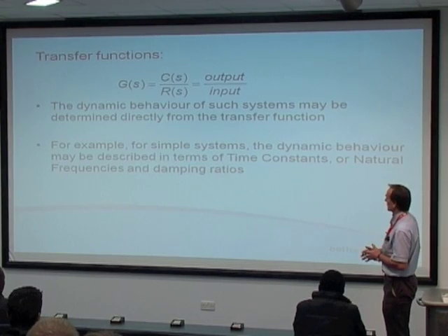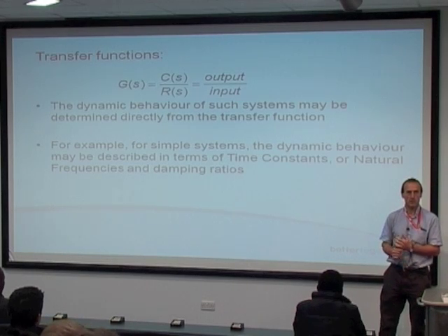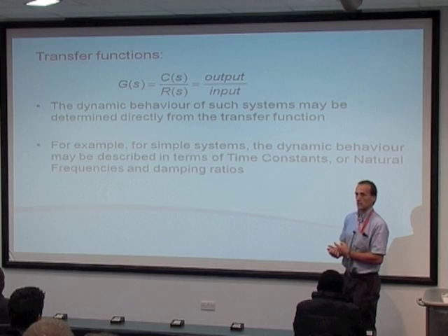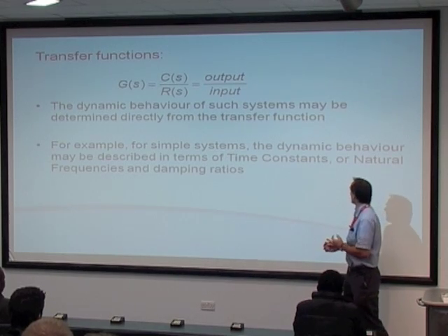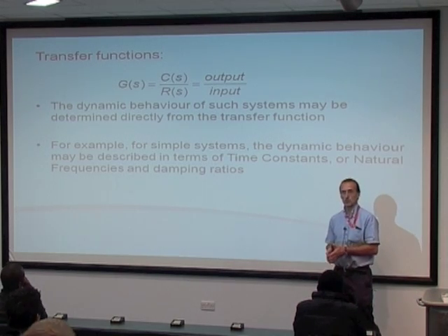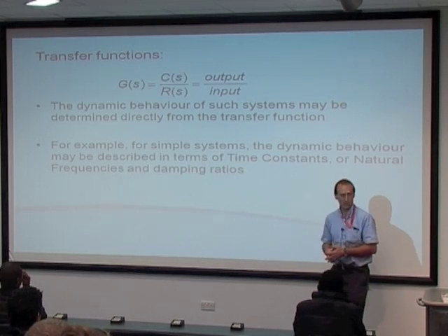So for example, with a simple system, we'll be describing that dynamic behavior in terms of a time constant if it's a first order sort of thing, or perhaps as natural frequencies and damping ratios if we're talking about second order. So as soon as we have the transfer function, we can say something about the performance.